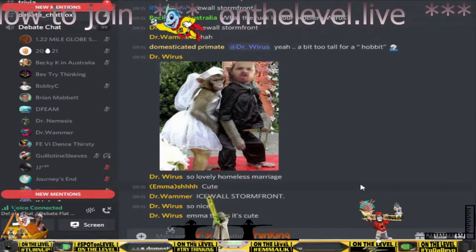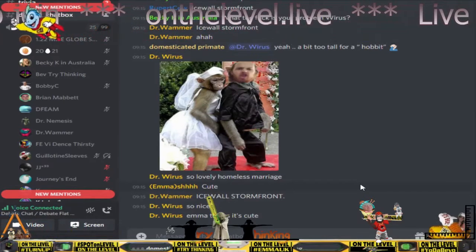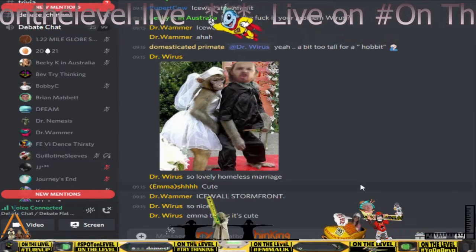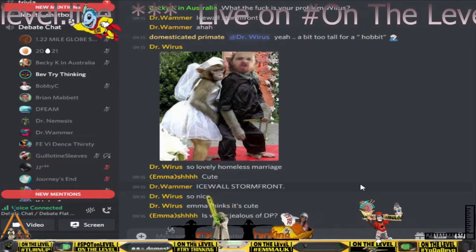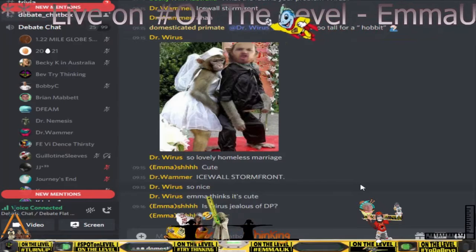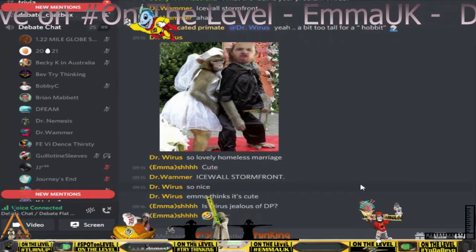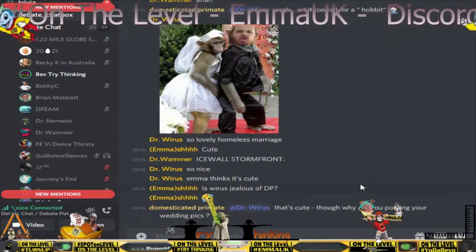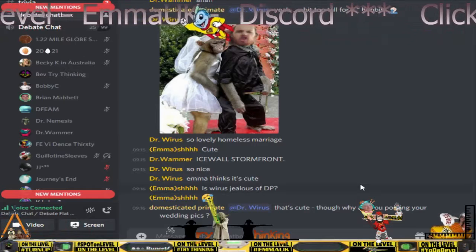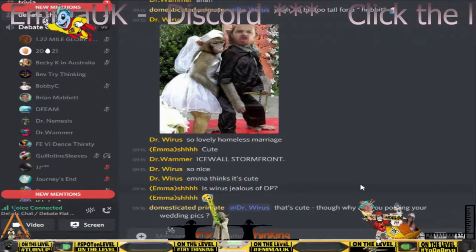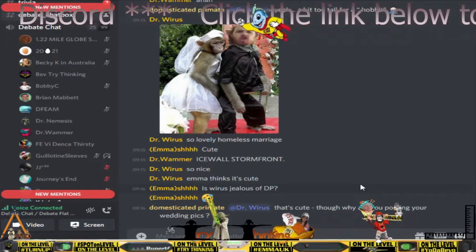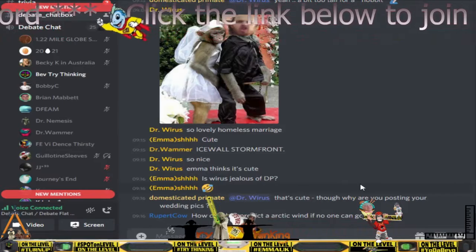What was it again? I said, how do you expect to measure? For instance, I don't know what numbers those represent. You said drop. I gave you the sagitta, so I'll give you the sagitta again, for that same distance as I told you. Yeah, 225 meters. The hump in the middle. From the chord, the distance between the chord and the arc is 1 millimeter. So if you're 225 meters from the end of the water levels, the chord and the arc. What are you talking about? The chord and the arc. 1 millimeter. I was assuming I was talking to a learned man who knows what a chord and an arc are.